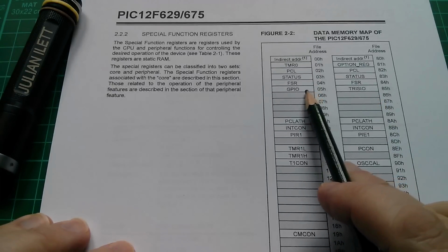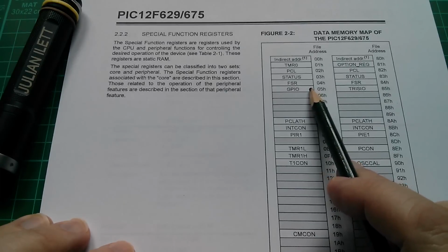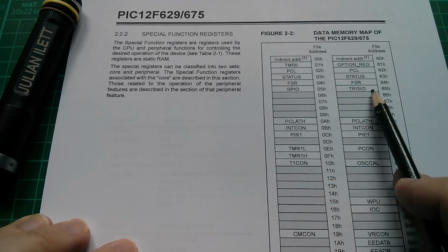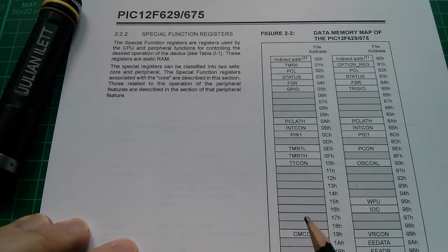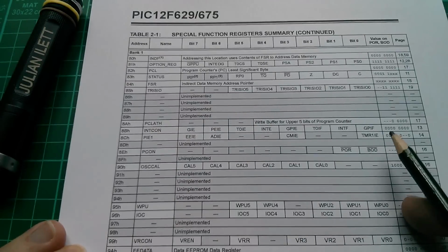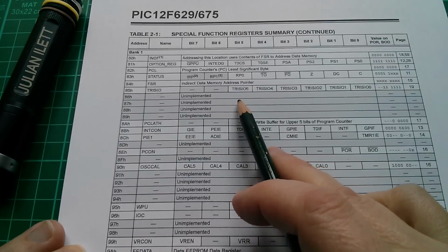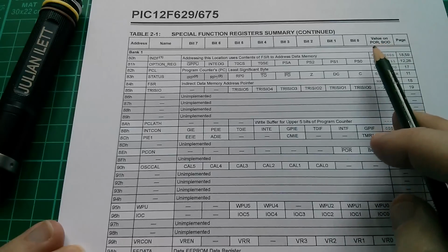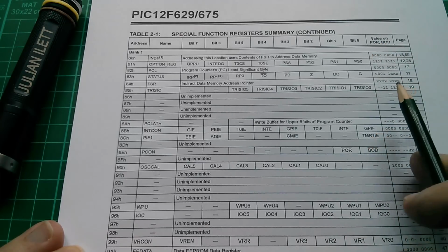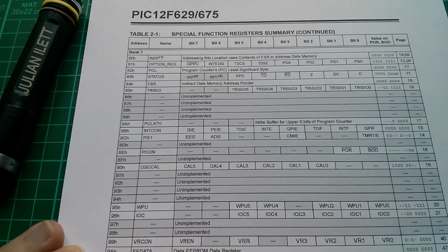So in the same way that we want to set the least significant bit in GPIO to go up and down to turn the LED on and off, we also need to do something with the least significant bit of TRISIO to make sure that that bit is defined as an output, not an input. Now you can see here from the datasheet, page 10, that the TRISIO bits, and there are 6 of them because there are only 6 I/O pins, all default to 1s when you have a power on reset or a brownout detect. So in other words, when the chip boots up, these TRISIO bits are high.